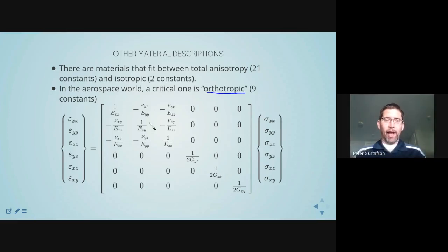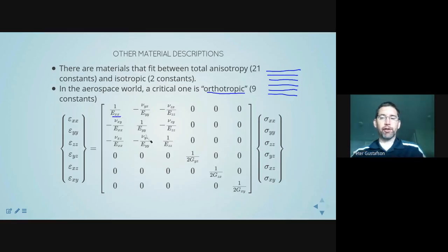And so when I'm saying that, this is something you can physically experience right there in front of you, where the response of the material, the constitutive response, that is the response that relates the amount of stress that you have to apply to get a given amount of strain, is now a function of which direction you are loading the material. A function of direction. So in this example, if we had a long fiber reinforced material and the fibers were all oriented with respect to the x direction, like so, we didn't have any transverse fibers, we'd get a very stiff modulus in the x direction.